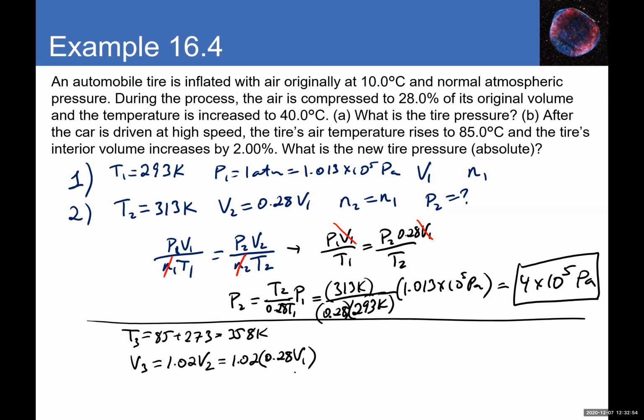All right. So then again, going from here, I can look at what I'm given, right? So let's say ideal gas law comparing state 3 to state 1. Remember, in my state 1, I had temperature 1, which is 10 degrees. So that's actually, all right, I made a mistake over there, 283 Kelvin.